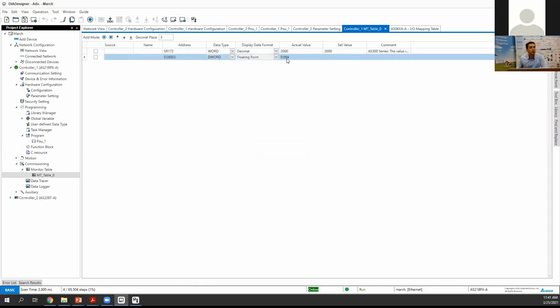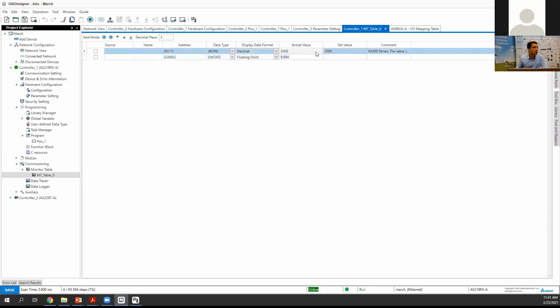Here you see more or less 10.0 volt. For 5 volt, for instance, here you see directly 5 volt. So it makes it simple for us. The CPU directly converts it, so you don't need to use an additional instruction to scale it. Okay, so this is how analog actually works. It is quite simple. Let's go to the programming part.